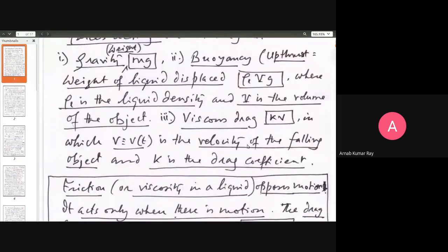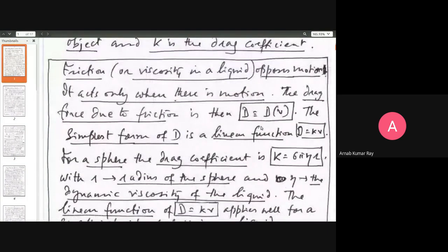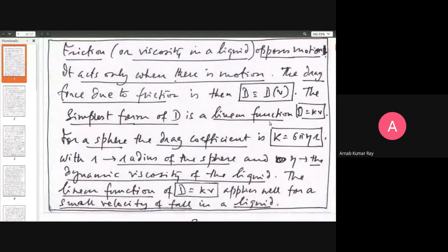Also, we had some discussion on this point. The fact that an object travels through any fluid medium, like water or air, means that the viscous properties of that fluid will also come into play, in as much as it will offer a resistance to the motion. If there is no motion, this force will not come into play. So this force, the resistance, is a function of the velocity. There is no mathematical proof of how we choose this function; usually the answer comes from experiment.